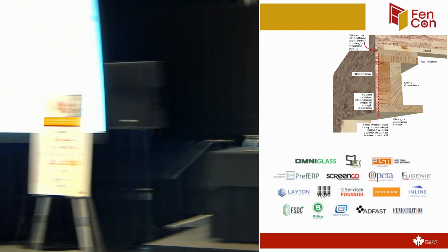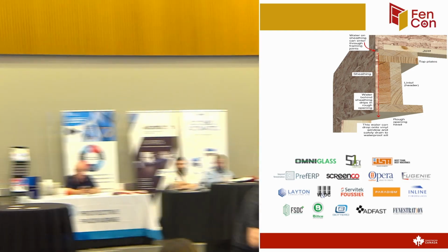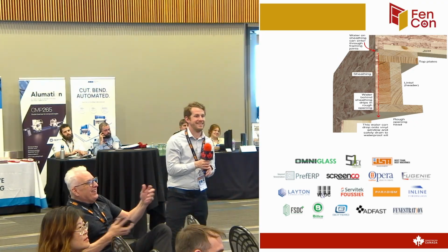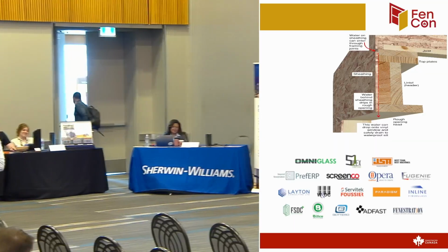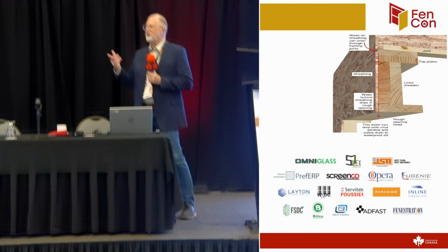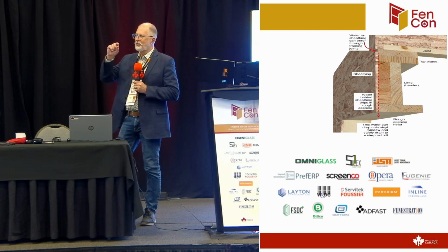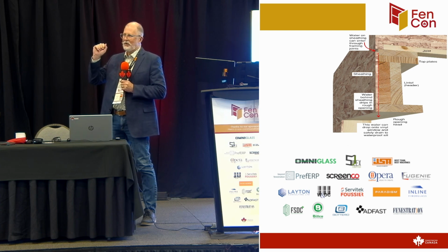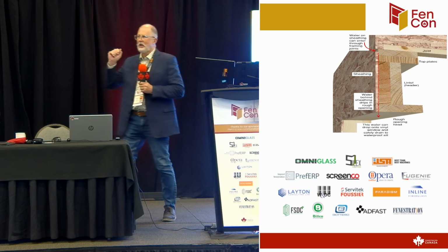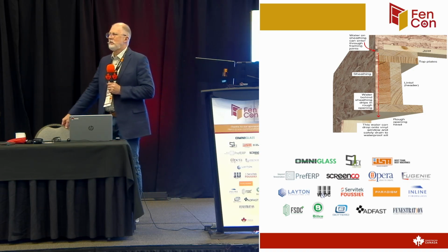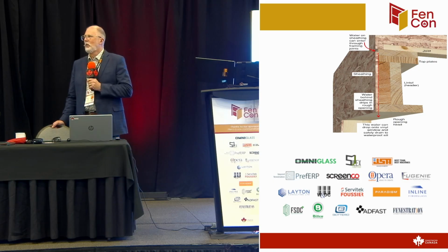Hey man, what about doors? Doors and the sill. Well, we could spend another hour talking about that, but it's the same principle. The CSA now requires them to have a space of 3/8 of an inch. On doors? Yeah, that came in 2019. I've never seen it done. No. How many rotten sills have you seen?